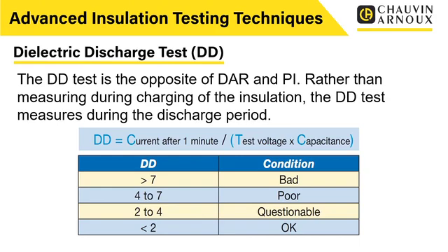I believe this is better for detecting certain faults, particularly within multi-layered insulation. So there are applications where this would be better than others. And as I've said before, sometimes people will apply all of the tests, or a couple of the tests together, just to collate the insulation and make sure they're all giving a good reading, rather than a lower reading on one where you're getting good readings on others, and that might indicate something that you need to investigate further, shall we say.